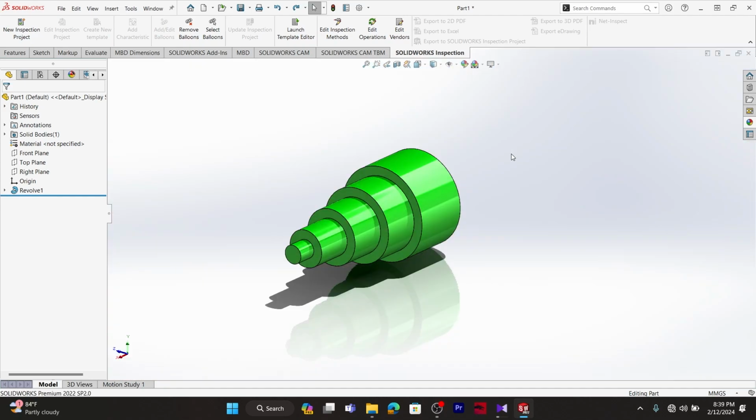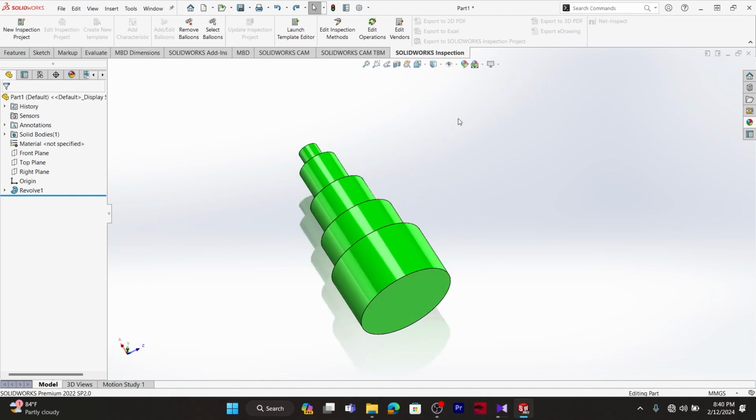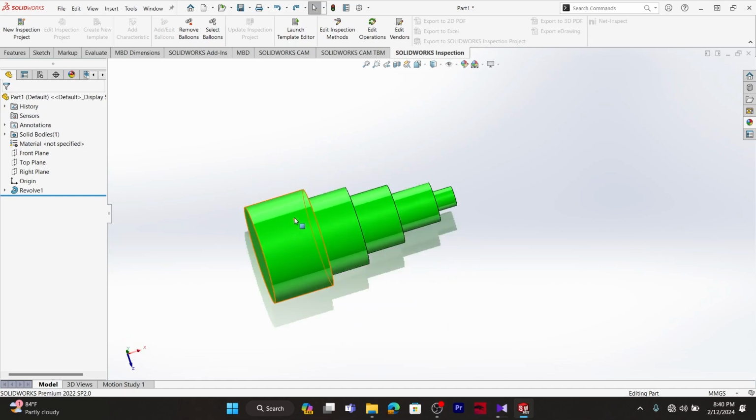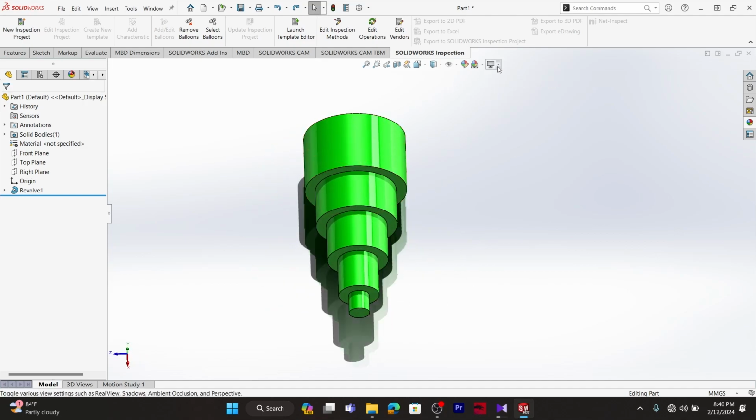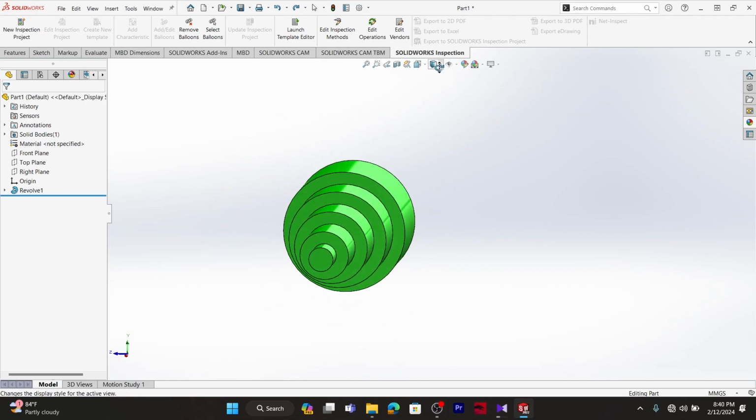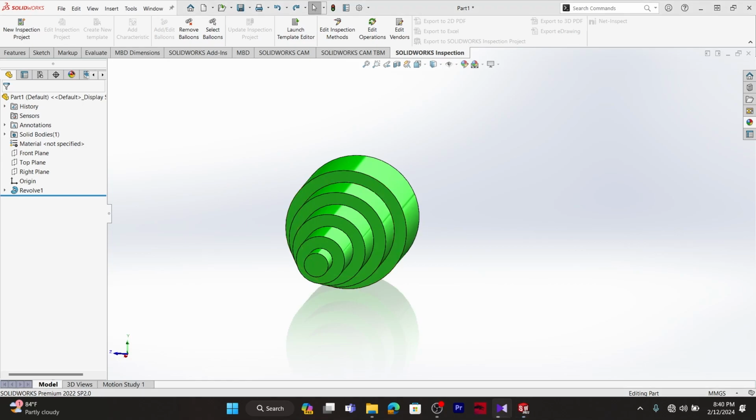Now we have some advanced options here in this view settings. So go to view settings, and currently shadows in shaded mode is checked. Let me show you what this thing is. For that, I'll orbit my drawing so that the shadows are visible. So right now you can see these shadows here, so I'll just go to this and deactivate this. And the shadows are no longer visible here. So that's the shadow option. I'll just activate it. I do want to see the shadows here. It makes the ground plane pretty visible.